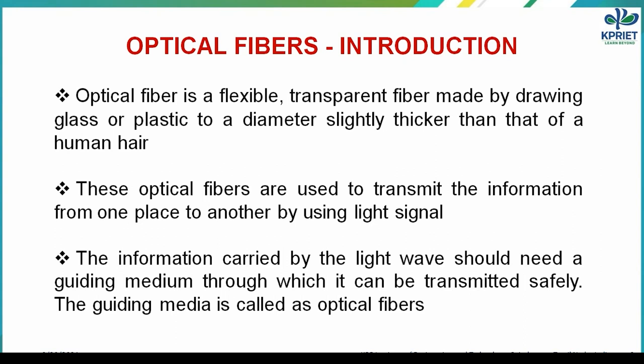Optical fiber is a flexible, transparent fiber made by drawing glass or plastic to a diameter slightly thicker than that of a human hair. These optical fibers are used to transmit information from one place to another by using light signal, that is fiber optic communication. The information carried by the light wave needs a guiding medium through which it can be transmitted safely. The guiding media is called optical fibers. So optical fibers act as guiding media here, and light signal acts as carrier wave which carries the information.